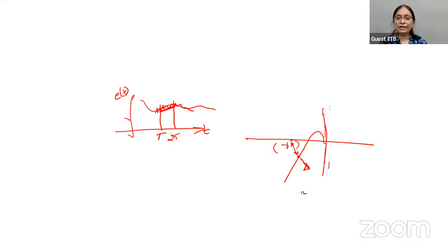One can look forward to adaptive ways also. The adaptive part is mainly to consider the nonlinearity of the system, right? So when the system is pretty nonlinear, or the environmental factors are changing drastically, such that your system transfer function is changing, then adaptability comes in. So intelligence is more towards considering my control structure as fixed, which we fixed as PID.